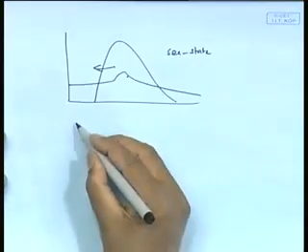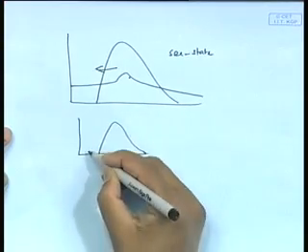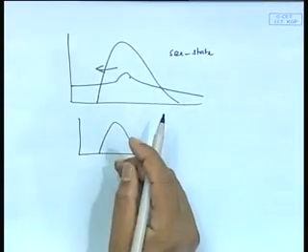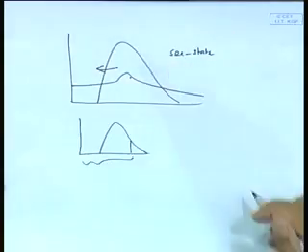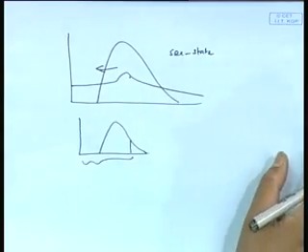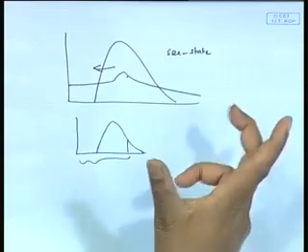So, there is this issue of tuning, that is important, and this also tells us why small boats are always bad typically. Of course, you can always see from acceleration, which is omega square into h, there is a square term involved, and obviously you see what happens if this displacement spectrum is shifted further. The acceleration spectrum is obtained by multiplying each ordinate with omega square. So, if it is farther off, it becomes more area. So, obviously, if I have got larger omega e, then I have more acceleration. Makes sense, no? If it takes 4 seconds to have one oscillation, the entire thing comes in 4 seconds. Another ship, same distance I am traveling in 15 seconds. So, my acceleration is smaller.